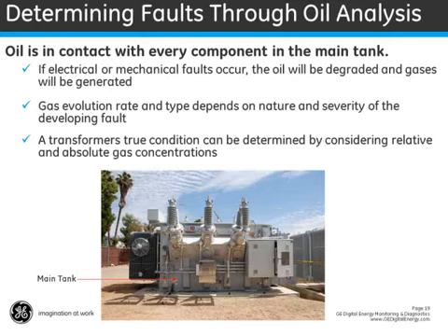Of course, oil analysis has always been a feature of good transformer management. Historically, it was limited to breakdown voltage determination and moisture in oil measurement, perhaps. From the 1960s onwards, with the advent of fault diagnostics, dissolved gas analysis emerged as the most important component of any monitoring program.